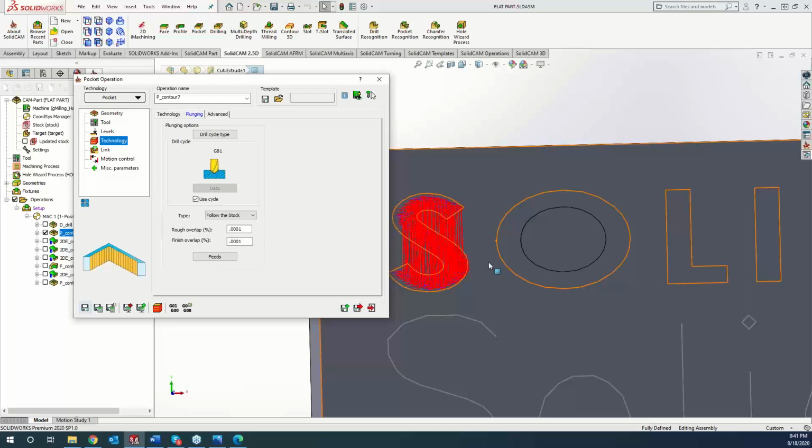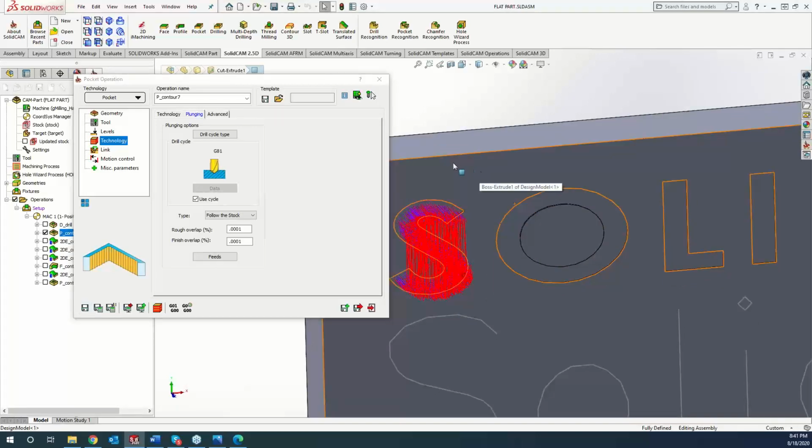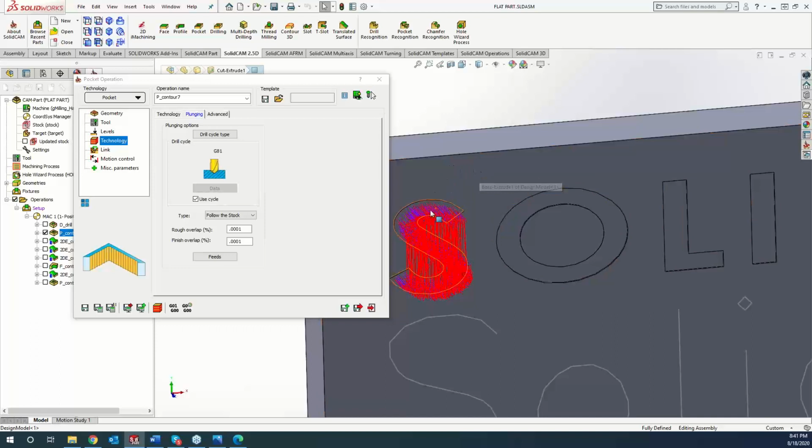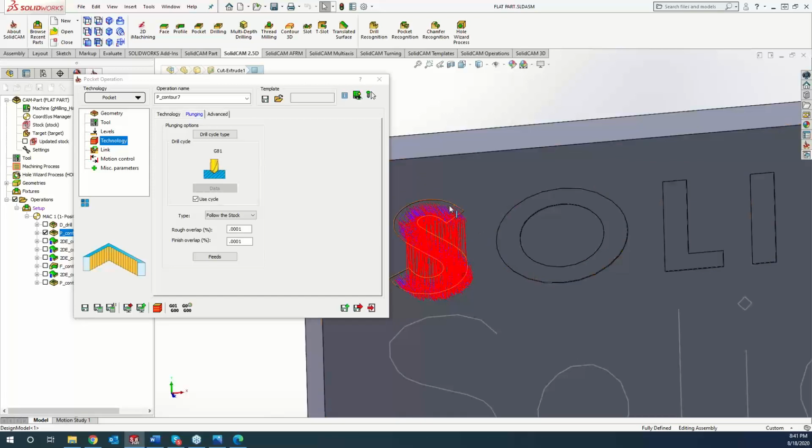But those will be gone over in a different night class. Yeah, great point. As we're coming down that 3D surface at an angle, the tool is coming down at the angle of that surface. Like Greg was saying, we can come in with the 5-axis at 90 degrees to that surface, and we'll definitely be showing you that in the future as well.